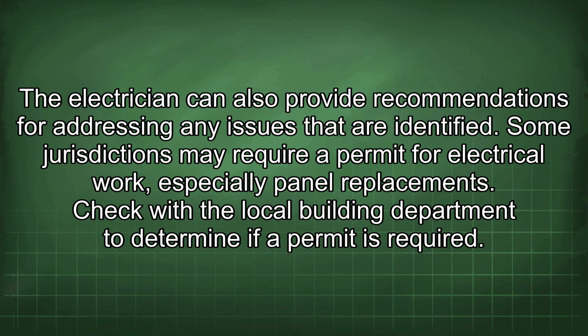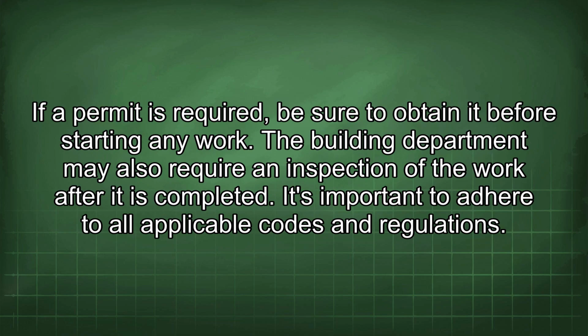Some jurisdictions may require a permit for electrical work, especially panel replacements. Check with the local building department to determine if a permit is required. If a permit is required, be sure to obtain it before starting any work. The building department may also require an inspection of the work after it is completed. It's important to adhere to all applicable codes and regulations.